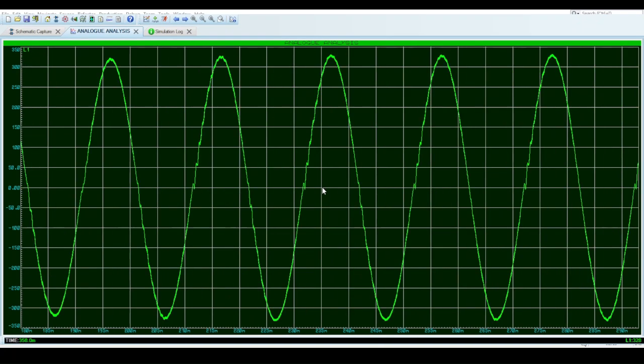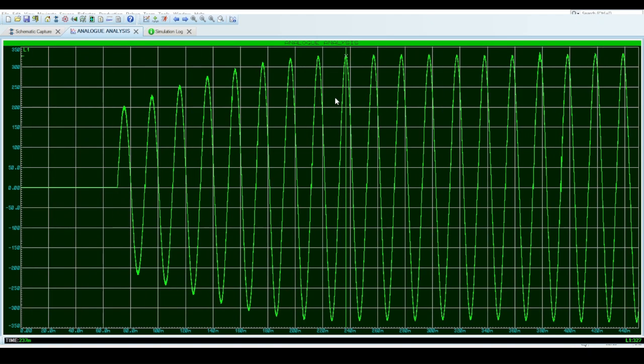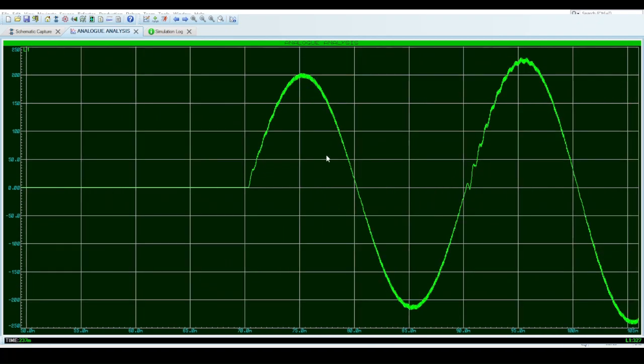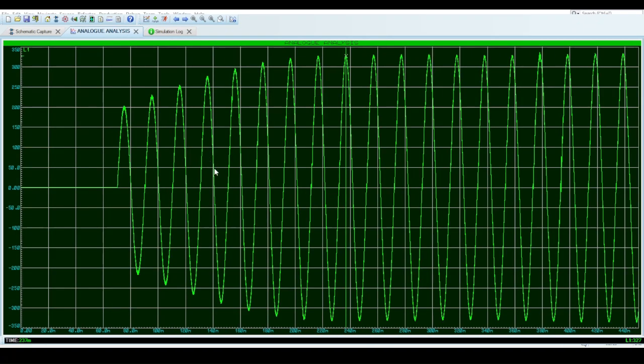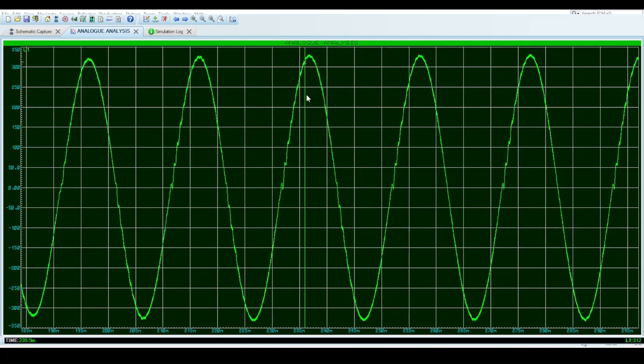As you can see, by the 240 millisecond mark, it's already at the set point, because it's actually checking at every point. It's not waiting for 10 milliseconds or anything like that. It checks at literally every point, because we're comparing an array. We're using a reference sinusoid. So just to show the difference in convergence speed to get to the set point, let's say it gets there at about 235, 236 milliseconds.